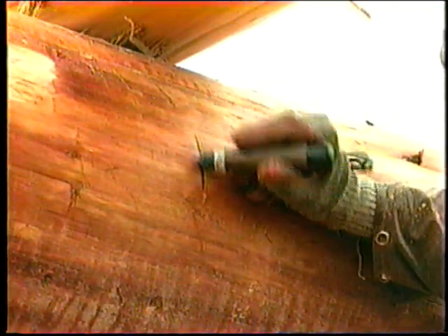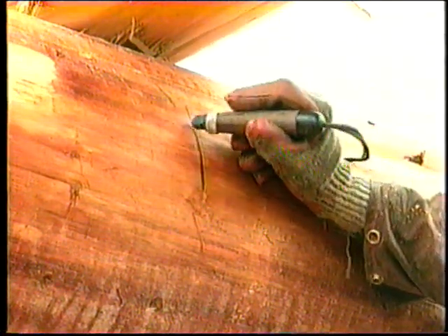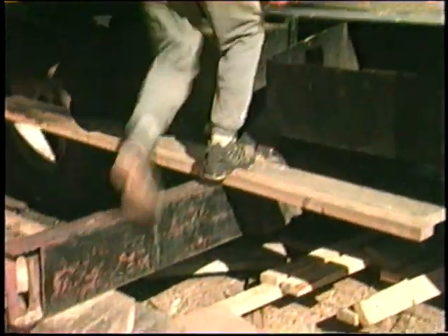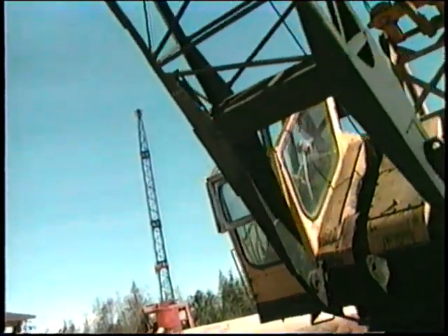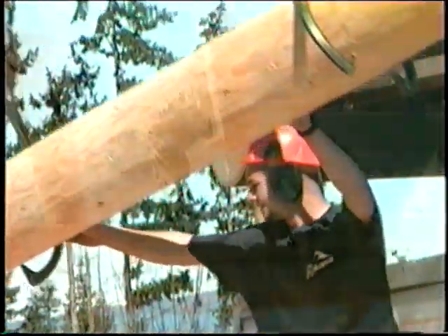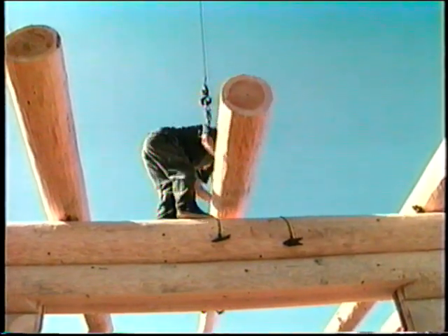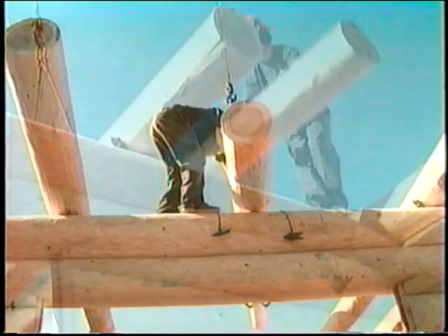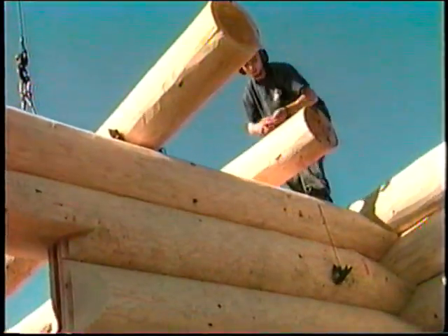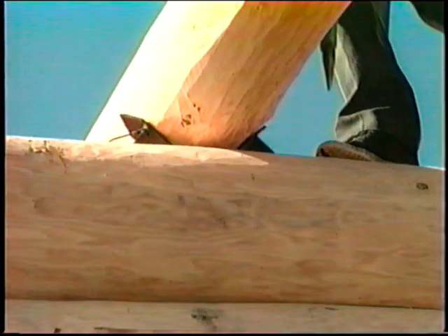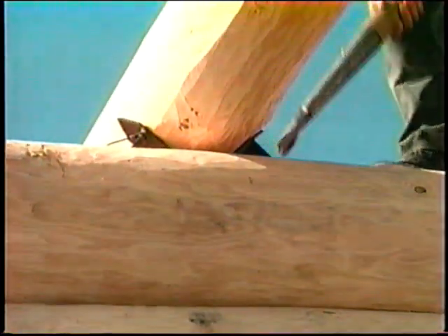Now mark off the centers for the joist locations, then place the selected joist material up on these positions. If there is to be a balcony or extension to one end, you may want to place the large end of the log in that direction. Place the large end of the joist or beam accurately on your mark, then block it with rolling dogs. Shift the other end into place and dog that end also.